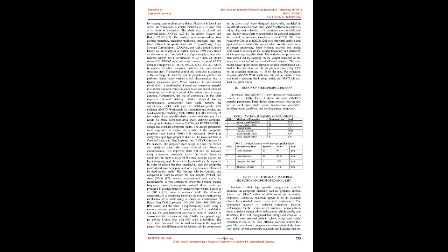Ramesh and Sangitkumar, 2015. This paper investigates composite hollow shafts built of carbon fiber reinforced plastics, CFRP, and glass fiber reinforced plastics, GFRP, for automobile applications. Failure analysis was performed utilizing maximum stress criteria, and it was discovered that the failure torque is significantly more than the design torque level.